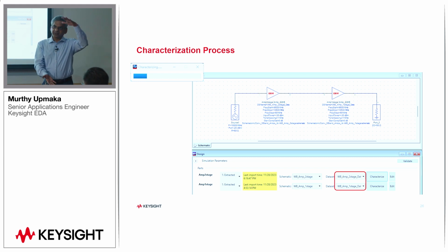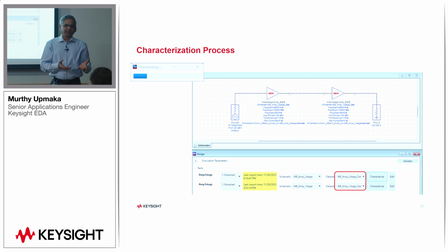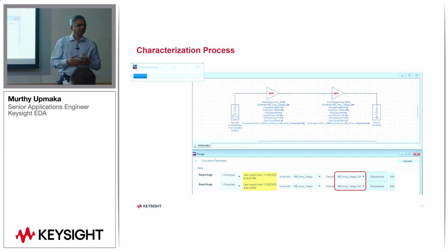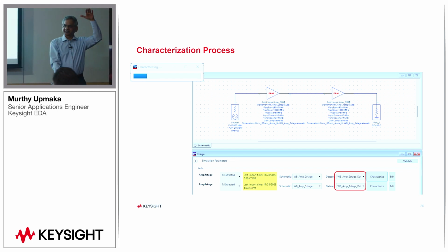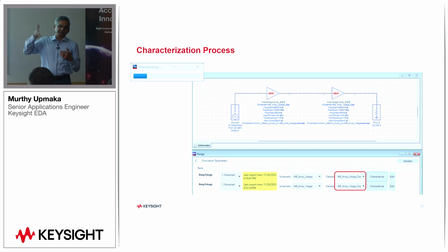It's a text file that will describe the performance of the amplifier. What are all the things that we need? We need the gain, the noise figure, the 1 dB compression point, the saturation, third order intercept point, maybe input-output mismatches, so the Z in, Z out you can get, and then the reverse isolation. So you capture all these as a function of frequency, and these are all captured as a function of power, right? Of course, it does the power sweeps and derives these parameters. If you have any other dimension in future, that will also be added.